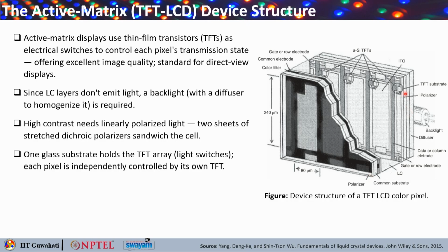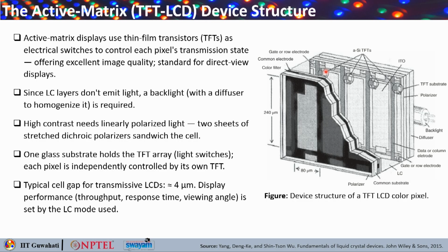Now look carefully, this is the TFT substrate. You require one glass substrate that holds the TFT array, which are the light switches marked here, amorphous silicon TFTs. So you can see that you are able to control each pixel independently with these TFTs.